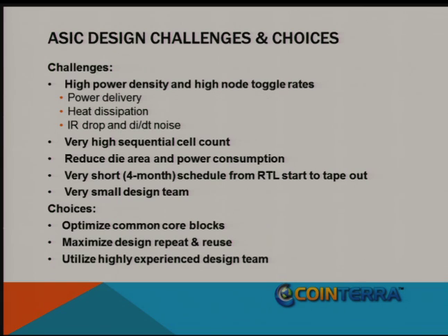One thing that worked in our favor was that the design naturally provided a high degree of repeat and reuse. Within the hash engine, we have the same or similar stages repeated 128 times, and at the die level, the same hash engine is repeated 120 times.